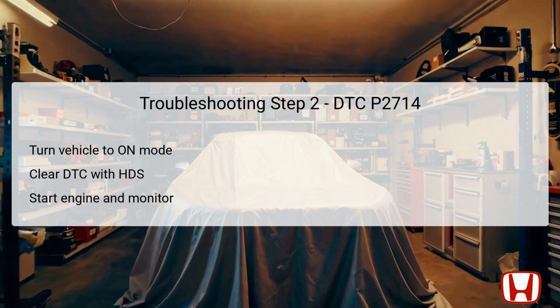HDS. If the HDS indicates that the DTC has failed once again, it confirms that the malfunction persists. In this event, the technician can duplicate the failure, while a comprehensive overview of the issue will also include checking the freeze frame data recorded with the DTC for detailed conditions under which the error occurred, making troubleshooting more effective.